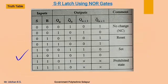So this is the summary of all the conditions which we have discussed earlier. This is our case 1, in which S is 0, R is 0. This Qn and Qn complement are the output state before applying the inputs, that is named as the present state. This Qn plus 1 and Qn plus 1 complement are the output state which is named as the next state, which we get after applying the inputs.